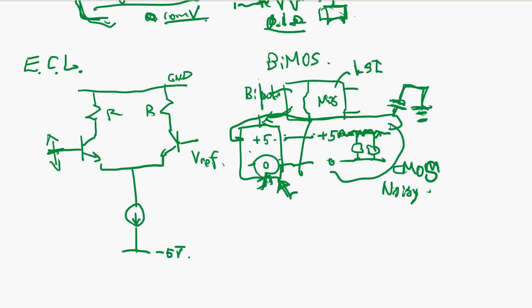Okay, so the swing is about 600 millivolt. And for 600 millivolt, you want to have a comfortable collector voltage for the transistor. So say this is 600. So this voltage, we think about the output.